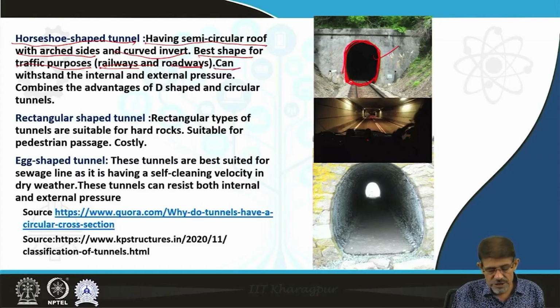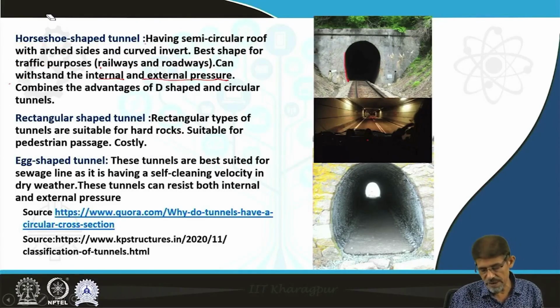And this structure can withstand the external and internal pressures, and therefore this type of tunnel has the combined advantages of the D-shaped and circular tunnel. Therefore, for traffic tunnels we are preferring this type of horseshoe tunnel.